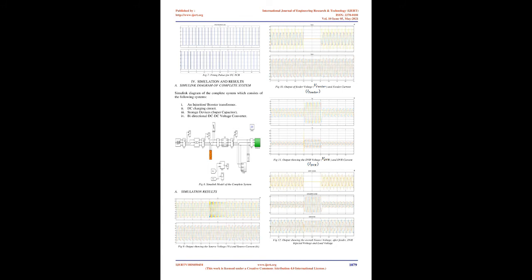Basically, the turning on of the thyristor is delayed with respect to the peak of the voltage applied in each half cycle. So, the period of conduction of the current is controlled as presented in Fig. 2. For any delay of the thyristor by an angle α, with 0 ≤ α ≤ π/2, with respect to the voltage crest, the reactor current is given as follows. It is obvious that the current magnitude in the reactor can be varied continuously by the delay angle, from the extreme, α = 0, to the zero level, α = π/2, as presented.